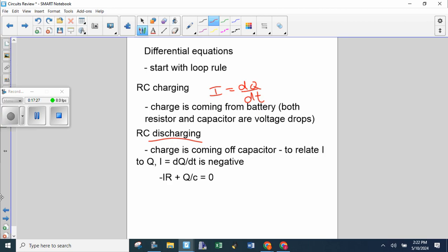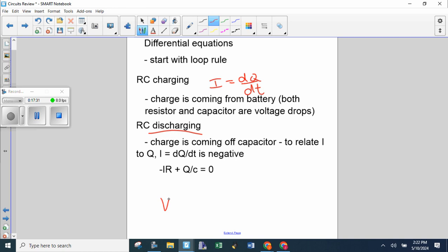Okay? The other differential that you're going to see would definitely be with the voltage on an inductor. That's the minus L di dt, the voltage on the inductor. I don't usually put the minus because I take care of the minus when I mark the high and low energy side on the circuit diagram. But again, on your equation sheet, it's going to say minus L di dt.